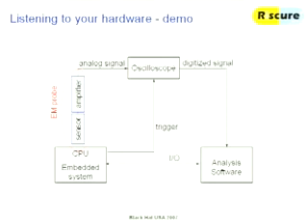What we also have is an external trigger, because when you're running something and it's running pretty fast, if you just hook on your oscilloscope and wait till it comes by, you won't see it. So you do want very accurate triggering to find your program.